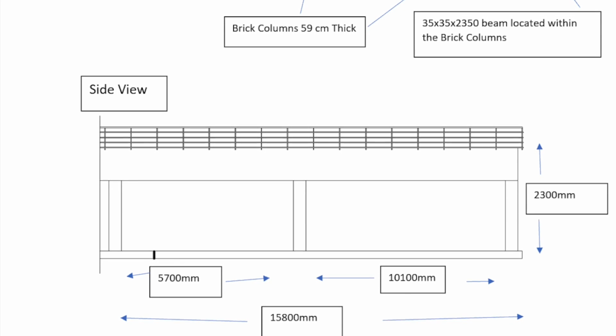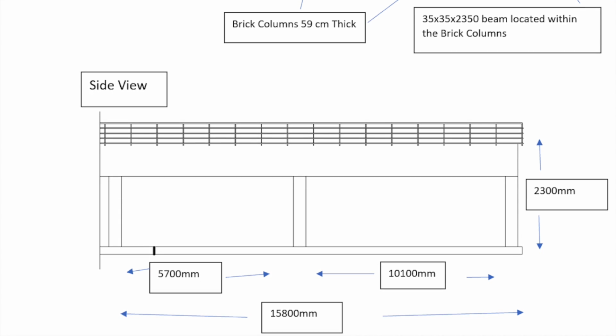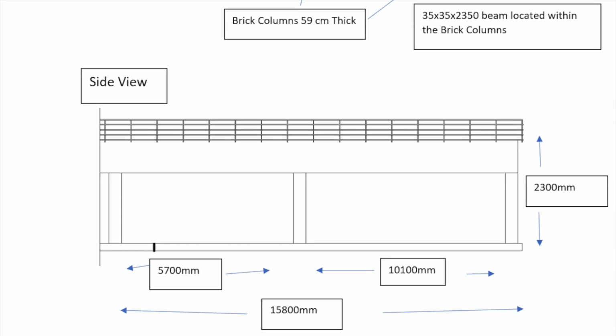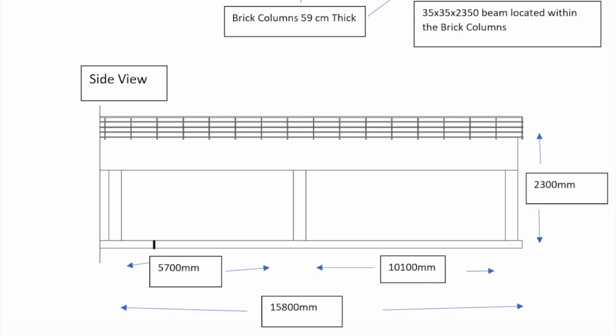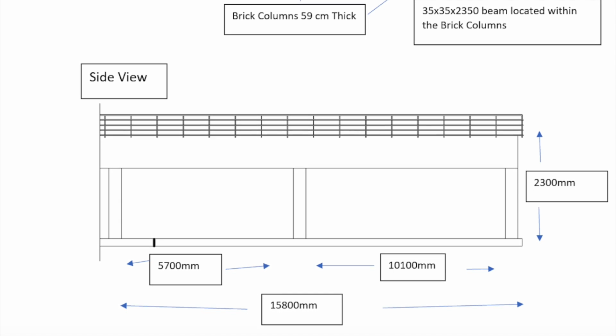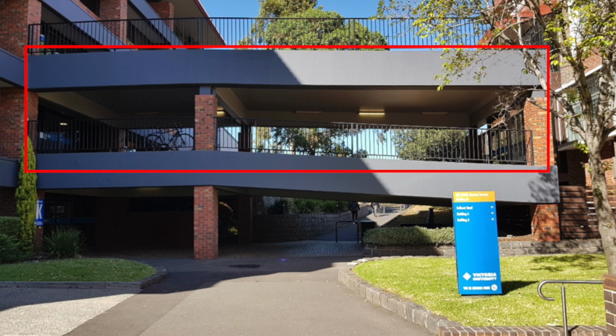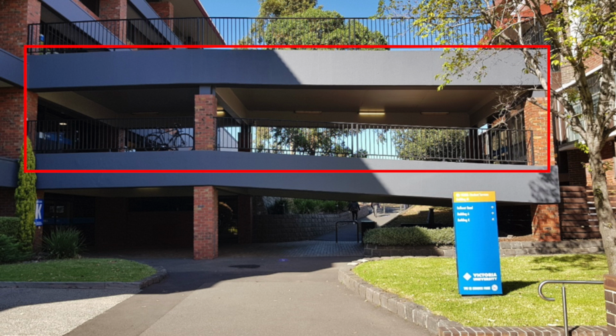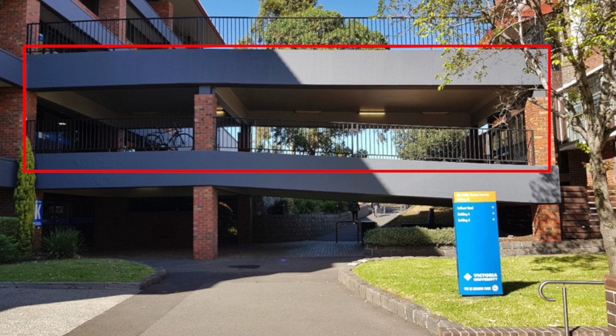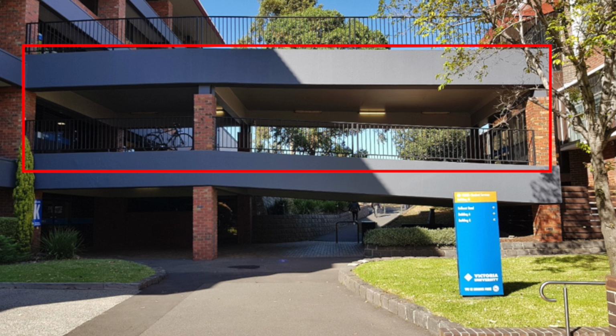We as a group were able to establish these measurements by measuring each component 3 times, then dividing by 3. Then we had to work out the uncertainties by subtracting the lowest value from the highest value, then dividing it by 2. We also worked out how to find the density of each element within the bridge. We also found the volume of each beam, which is found by multiplying the length by the width and by the height. As we multiplied the density and the volume, this gave the mass of each section of the bridge.